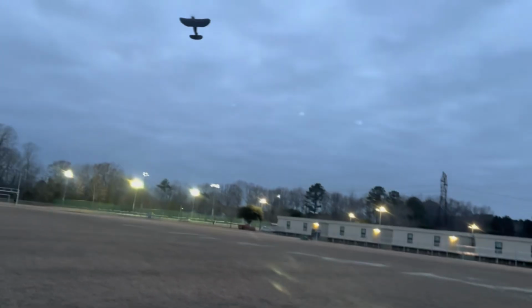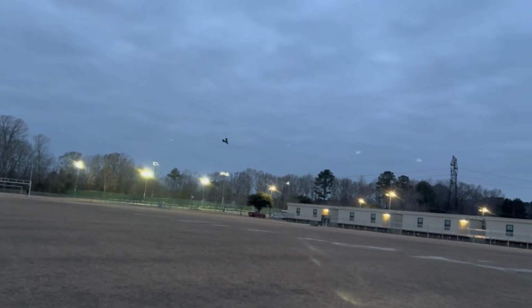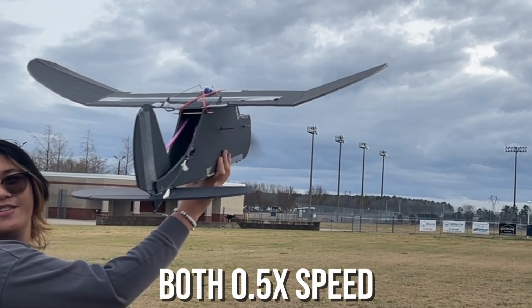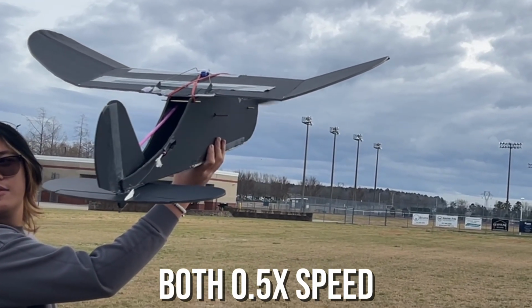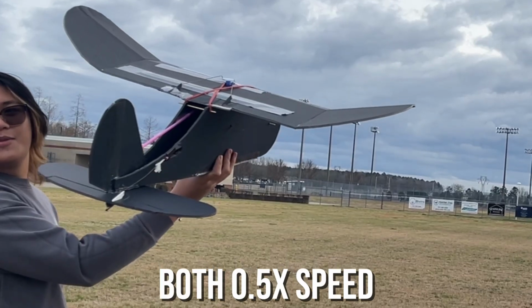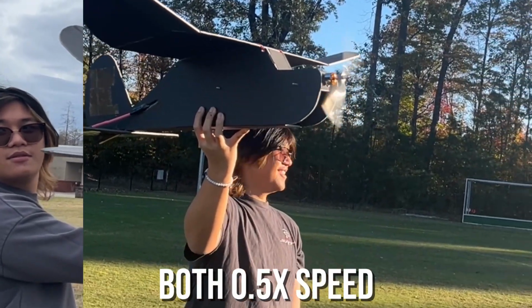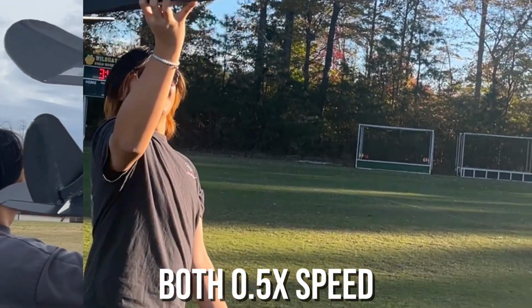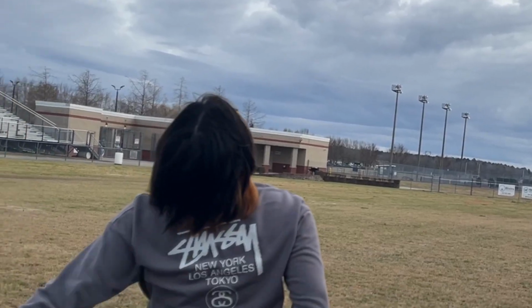Instead of just guessing what went wrong, we treated it like a diagnosis problem. We went back and compared time trials footage to our earlier successful flights, and one detail stood out. The propulsion system wasn't producing the same thrust. The propeller was visibly spinning slower than before, which pointed to accumulated motor shaft damage over time. That combination, structural failure from weak wings and reduced thrust from a damaged motor shaft, explained why time trials looked so different from our early flights.